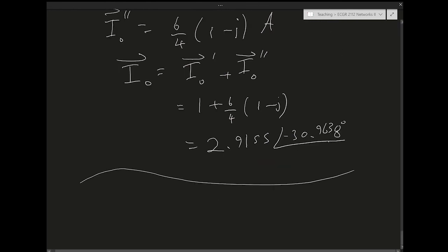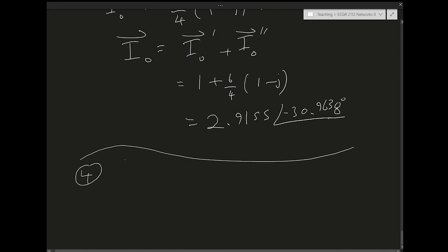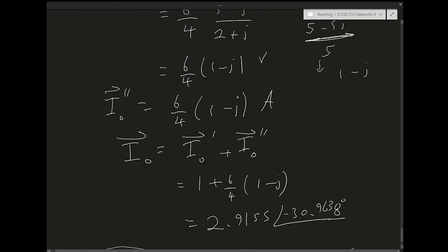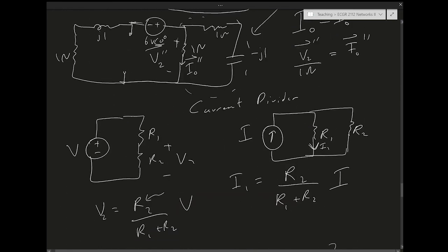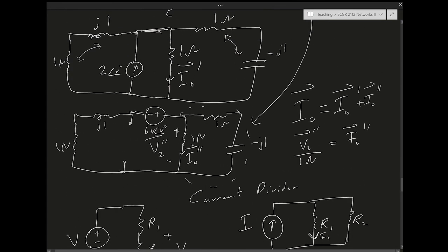The fourth technique we want to review now is the technique of source exchange, which is very similar to the Norton and Thevenin analysis techniques, equivalent circuit techniques. We just have to look at a source and lump it with some impedance so that we can convert it from one form to another, from a current source to a voltage source. I'll remind you how to do that. I hope you studied it in Circuits 1. But anyway, it's very simple. It's all based on Norton and Thevenin, which we will cover next too.